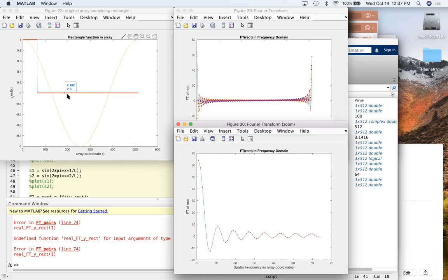That's because you get less of the higher frequency cosines within your rect function. The amplitudes of the high frequencies go down. You can think of it as needing to make a big hump, and then sharper and sharper edges. Those are done with the high frequency cosines, and they have lower amplitudes. I see. I think I understand now. Thank you.